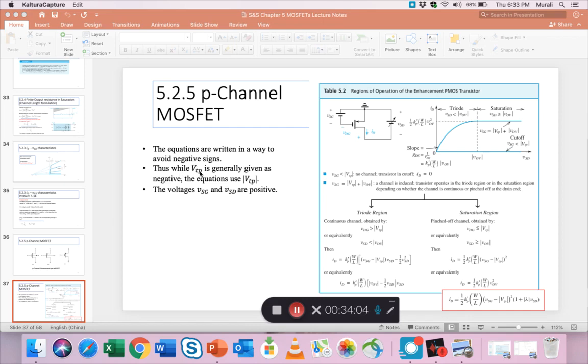Thus, while VTP is generally given to us as negative, remember VTN was for NMOS. We are generally given VTP as a negative value like minus 0.4, but in the equations we just ignore the negative and just use the absolute value. That's why you have these straight brackets, okay?